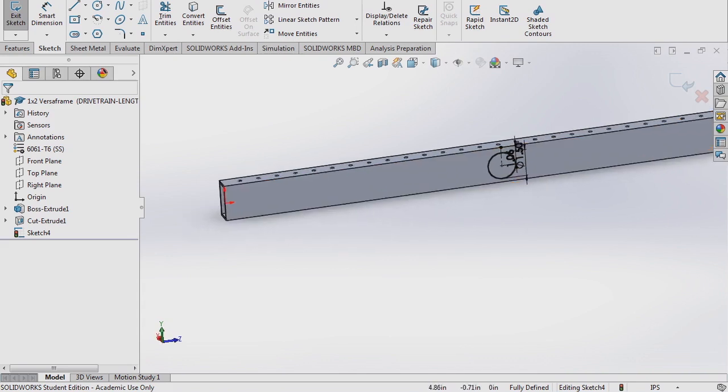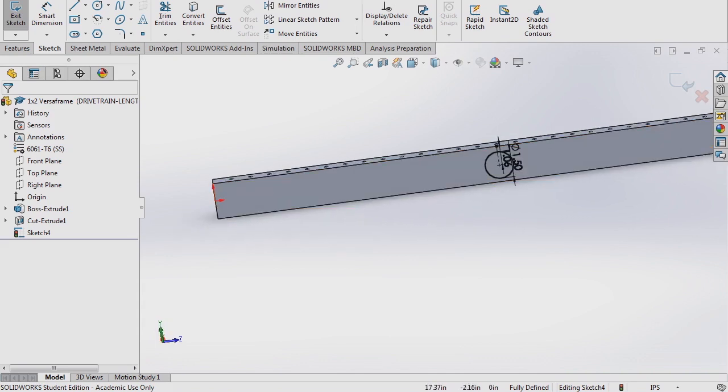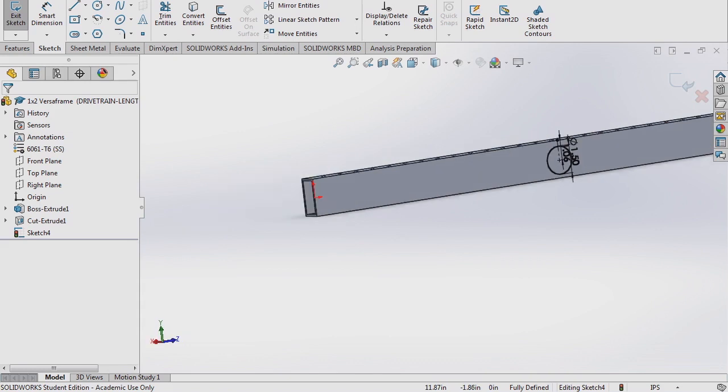And chain actually stretches. So to use chain effectively, it always has to be tight. Same with belt, it always has to be tensioned and tight. But because chain stretches, we need to be able to constantly retension it. So actually in a drivetrain, you can pull the sprockets further apart to tension the chain.